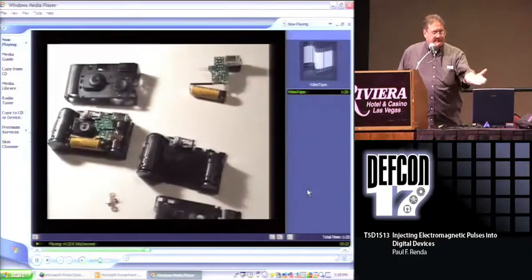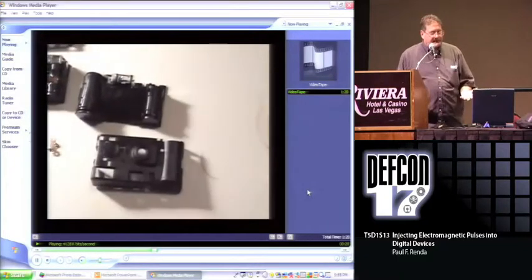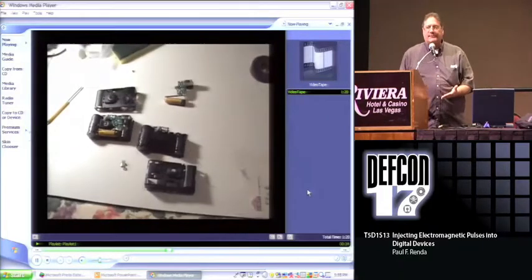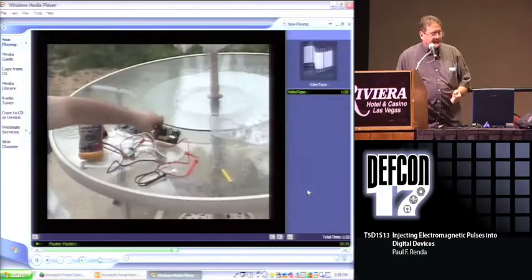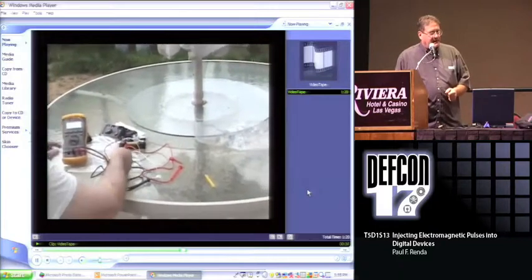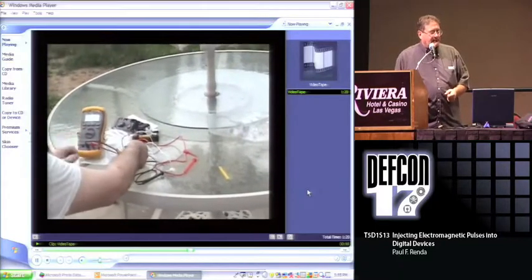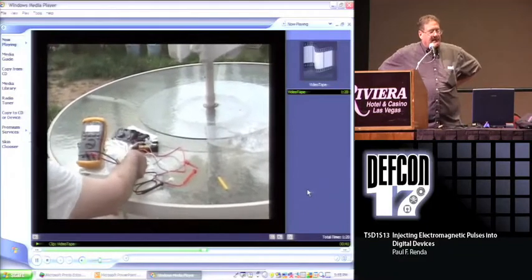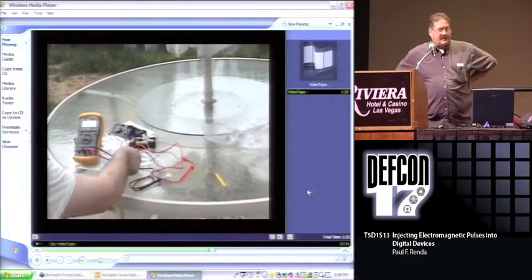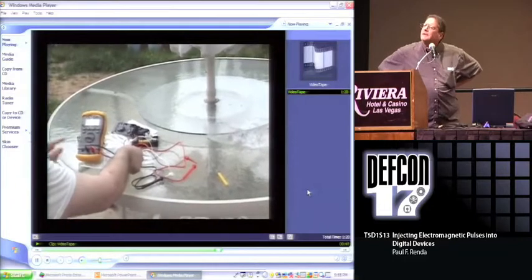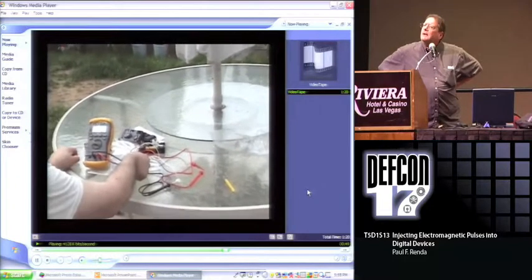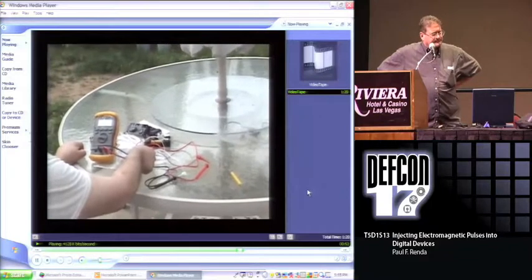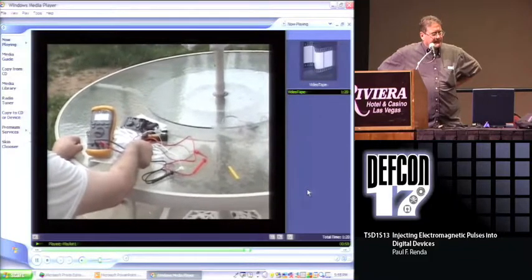All these disposable devices contain pulse devices. I took it apart, measured the capacitance, measured the voltage that it'll charge, and I don't know if you see too well, but I'm charging it up. I don't have the video turned on, but it charges about 300 volts. And I measured the capacitance at, well, it's on the next screen, but 100 microfarads, I think.